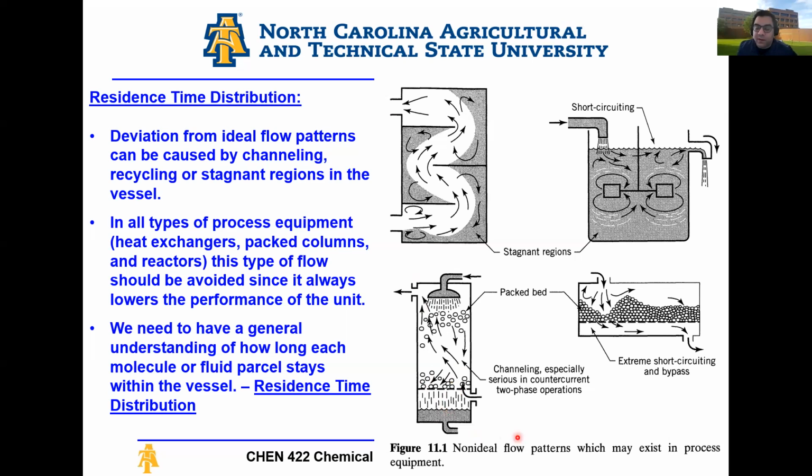And let's say here I have a countercurrent packed bed. I introduce liquid from the top, so I'm spraying liquid from the top, and I have gas entering from the bottom. And channeling is when the gas basically sees a lot of resistance here, just ignores it and just zips out from the side. And this is the issue. One of the issues with dealing with gas is it's smart. It will always pick the easiest way out,